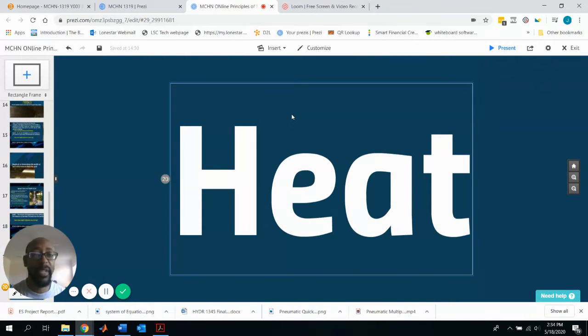Also, you have to be careful of the heat. The guy who was talking about the smithy, which is kind of a do-it-all lathe, was telling you, hey, cutting fluid, which lubricates and which cools, is always good to have typically. That's because you want to find some way to transfer that heat from where the cutting tool is actually going into your workpiece, because there's a lot of heat that's being produced in that process.